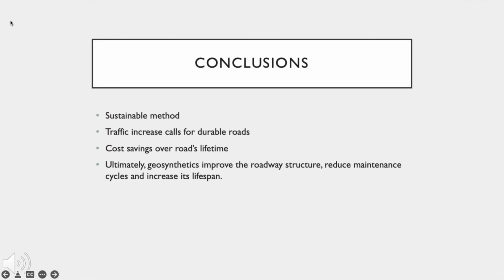So in conclusion, geosynthetics and pavement design is a pretty good method. It's actually pretty sustainable. You have to repair the road less, meaning less trucks come out to the field to repair it, reducing the carbon emissions. It also improves the roadway structure, and you reduce how many times you have to maintain it over its lifespan, and it increases its lifespan. So it also saves you a lot of money. And the need for durable roads is pretty important as traffic keeps increasing. So geosynthetics should be used a lot more often, and they're actually used pretty often, which is a really good method in this field.